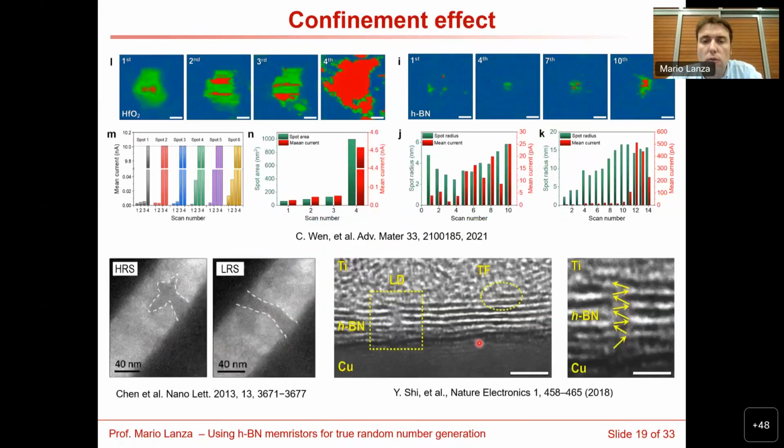So we have observed that across this path, you can produce two resistive states. You can form a filament of ions penetrating from one of the electrodes, and they sit here, and they trigger a low resistive state. But if we apply voltage of a different polarity, we can destroy this conductive filament and then generate a high resistive state. So with these two states, you can make memristors, and the memristors can be used as an electronic memory.